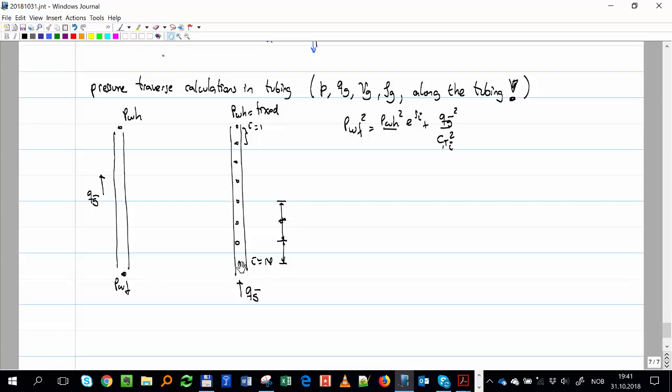Okay? If for some reason I had the pressure here, then I have to do the opposite. I have P1, calculate P2. Now this becomes the inlet to the next segment. Okay, if we look at this like a segment, now you have the inlet P1, that will be P2. Now you look at the other segment, this will be P1. You want to calculate P2, and so forth.